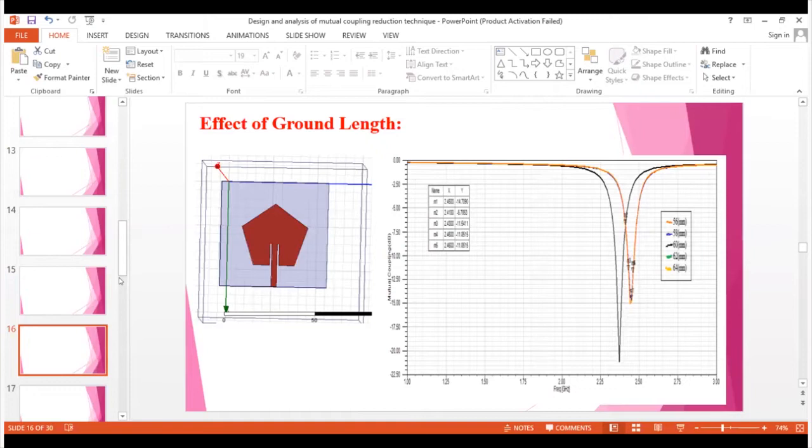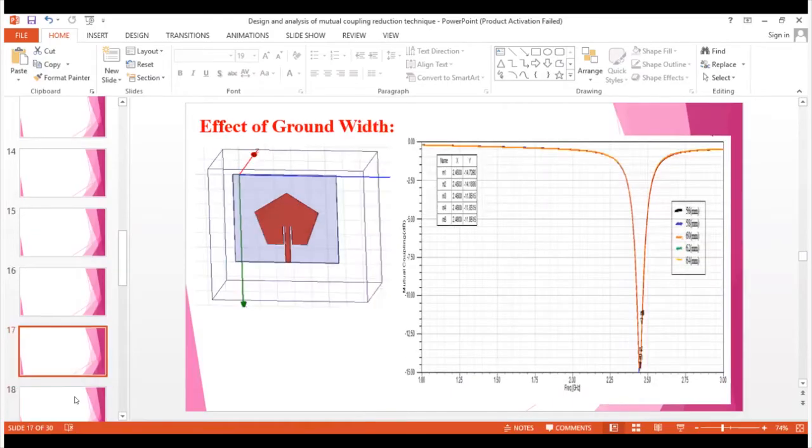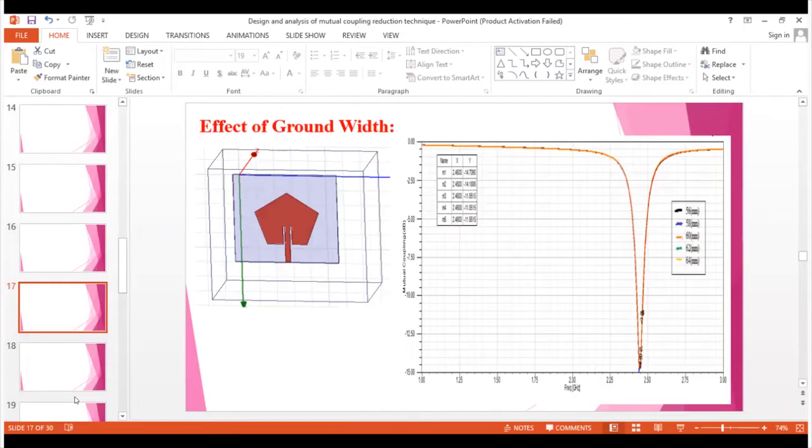As for the effect of the ground, the antenna impedance and bandwidth characteristics are typically affected, as long as the antenna located in the center of the ground plane is sufficiently large, even if the antenna radiation pattern is known to be affected by the ground. Regarding the feeding techniques, once the ground width changes, the feeding point is located in the middle of the upper portion of the ground plane. If the feeding is located at the bottom portion of the ground plane, the coaxial coupling affects the existing plane.